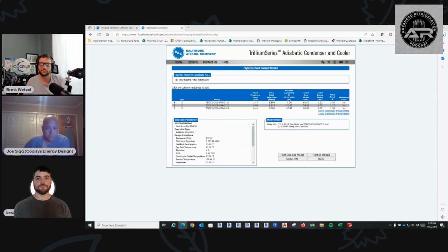We don't have a lot of load at night because the majority, probably a lot of that load, is your flash gas load. So all the VFD compressors, most of these manufacturers are sizing everything off of that peak flash tank load. Well, that VFD compressor may be the only one running in the middle of the night, and it can't keep up. Sure. It's just short cycling. Even the VFD is causing short cycling? Yeah. That compressor's running by itself? Yep. Wow, that's pretty amazing.